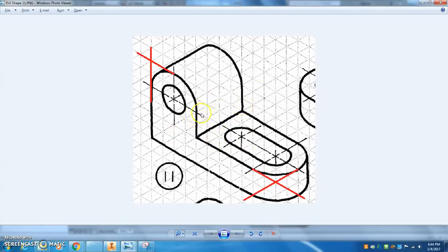The first thing I'm going to do is cut out this big area right here, which means I'm going to decide on a box to draw on the top of my big block, and I'm going to extrude it inward. And so the overall height of my object is 6, but if you see there's only 2 inches left here, so I'm going to take 4 inches of height out of this area. So I need to see what the dimensions of this area I'm going to cut out are. So if I go from either this corner out to where I made my cross here, or I could go from here out because this is the absolute max of that piece of the object.